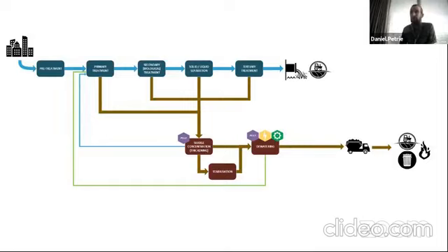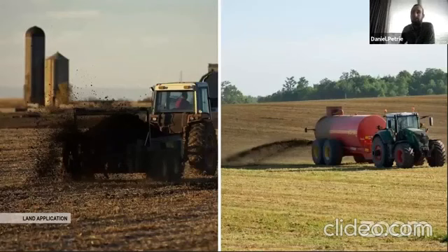So that's what land application can look like. There have been in the past very well drafted and strict guidelines as to what the maximum application rates would be. So how many kilograms of sludge can you apply to a hectare of land, depending on the quality of the sludge. And that quality is measured in terms of how stable it is, how many metals there are in it, and how many parasites there are in that as well.